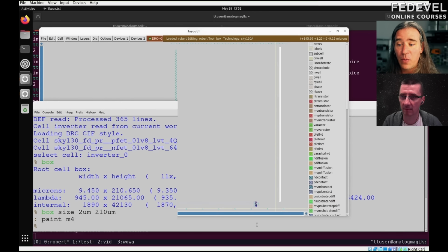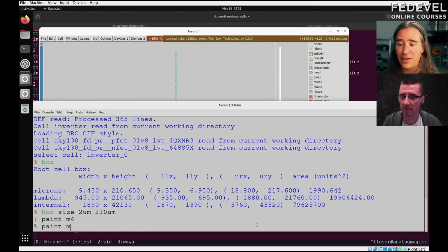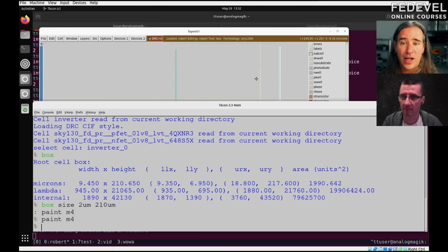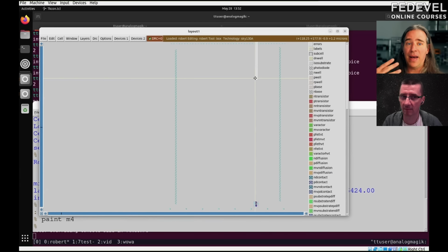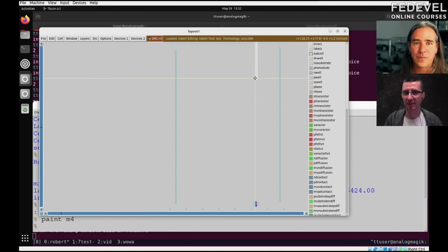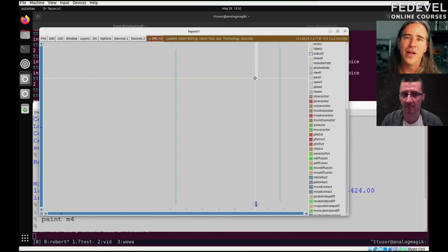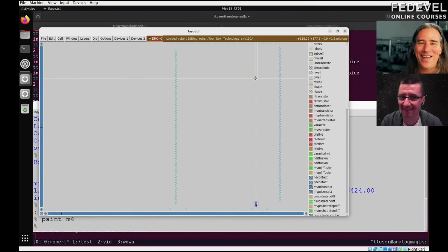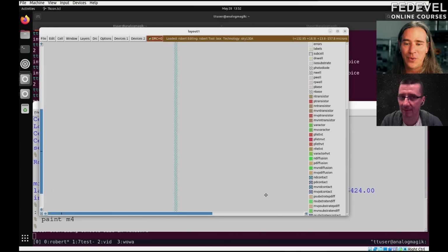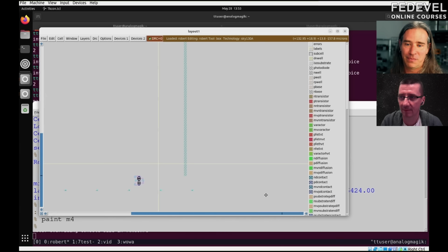And then, there's actually 5 metal layers. You're not allowed to use 5 because Tiny Tapeout routes power there, and every time it sees one of these rails, it'll drop some vias for you. So don't connect it to any pins here. It will be connected in the next step. You just give it the right name, V power, V ground, and then that's it. It will come from the sky and just be delivered to you. But the important thing is that you have to connect these to your circuit.